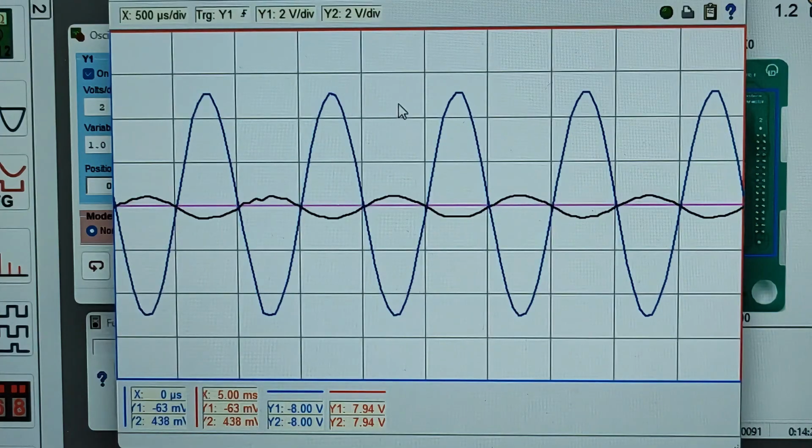Now, the amplification factor of our circuit could actually be computed as the feedback resistor over the input resistor. Feedback resistor is 1 megaohm. Input resistor was 100 kilohms. So that's 1 million ohms divided by 100,000 ohms, which also gives you 10. So the results on the waveform confirm the amplification factor of the inverting operational amplifier circuit we constructed earlier, which also gives a 10 amplification factor. The input was amplified 10 times at the output.